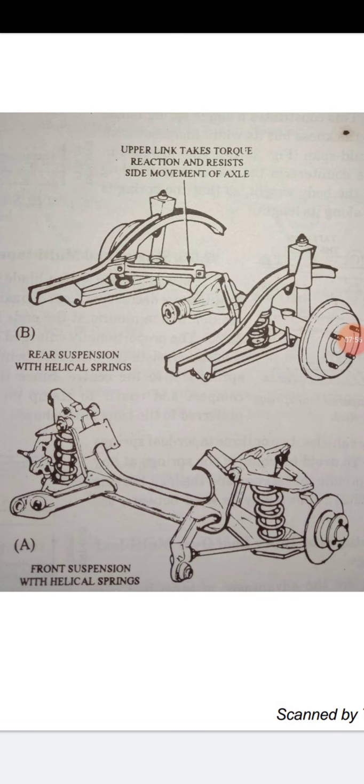Okay, now in a front wheel drive car, helical springs are commonly used to support the rear dead axles. You can see from the figure a layout in which the spring acts directly on the axle.